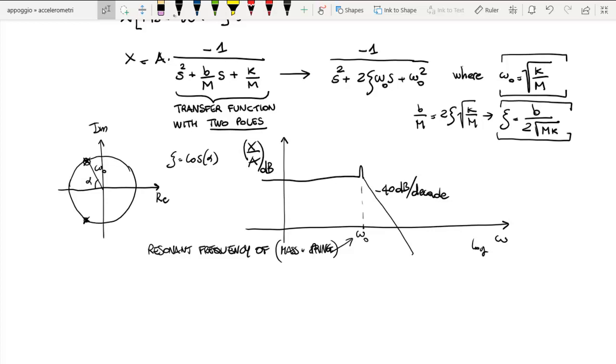And this average displacement is exactly x at low frequency and is proportional to the acceleration. So, as you can understand, it's much easier for us to then translate this displacement into an electrical quantity, because now the displacement is a stationary quantity. It's no longer dynamical.